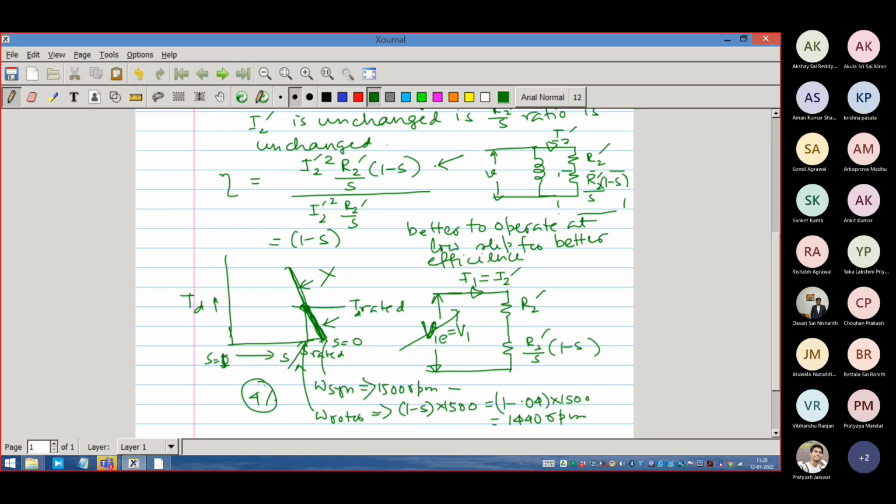And this variation is happening due to variation in the torque. Some torque it will operate here, some torque it will operate here, some torque it will operate here. This is the external world; the mechanical system demands this. I will just go to the corresponding RPM and, due to the mechanical torque demand, let the actual rotor speed vary.